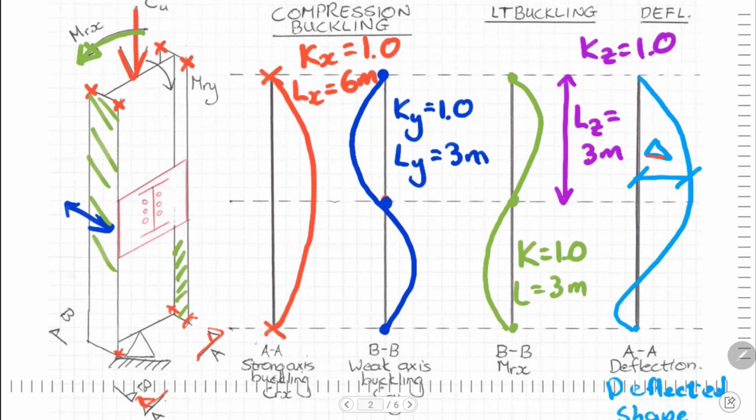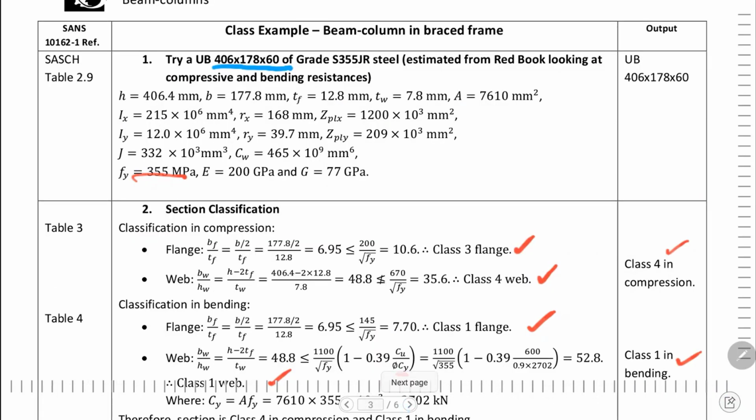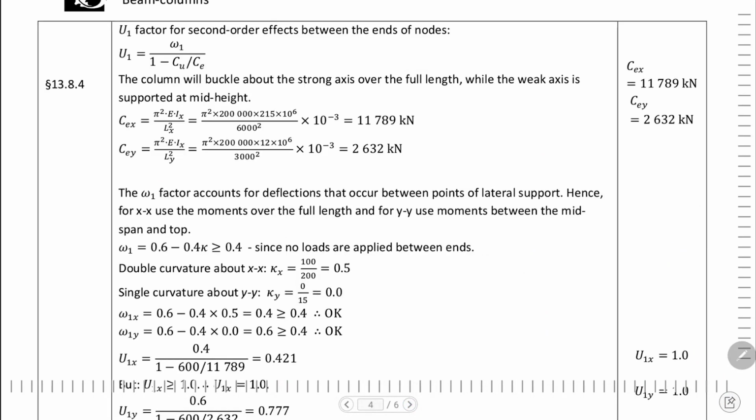Since we have the maximum moments at the end, it's probably not going to be a big deal, because where the P-delta effect occurs, somewhere around here, the moment's a lot lower. So it's probably not going to be a big deal. If the maximum moment was also there, then we'd have a problem. If there was a uniform bending moment, it would be a worse effect.